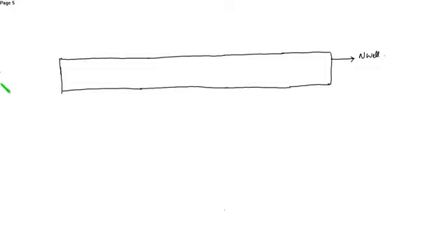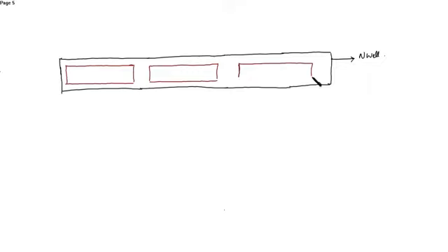Now after drawing the N well layer, next you have to draw the P diffusion layer. We need 3 P diffusion layers because we have 3 PMOS. So this is 1. Second one, and then the third one.